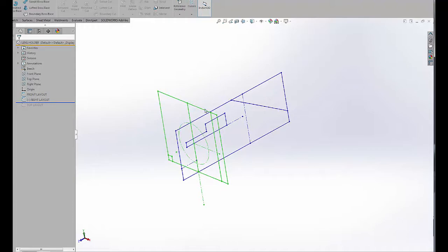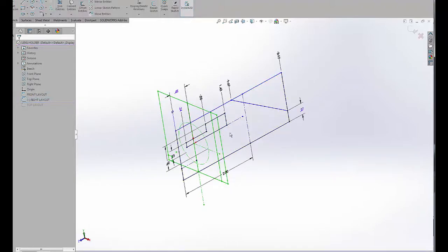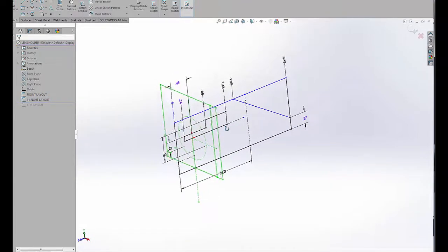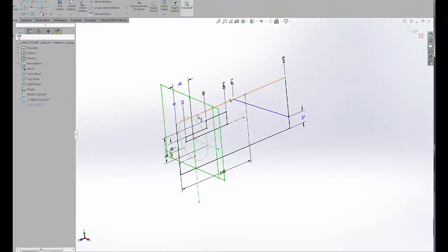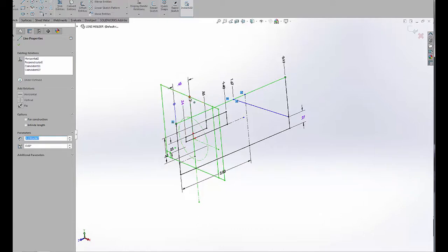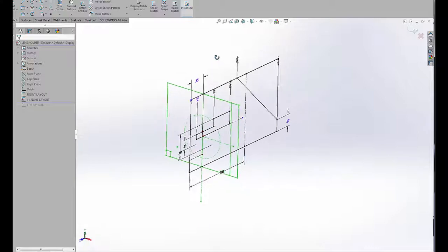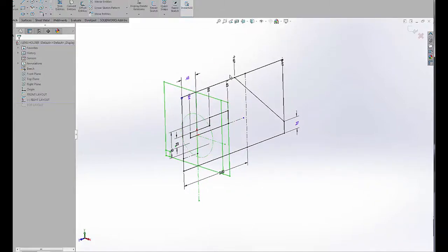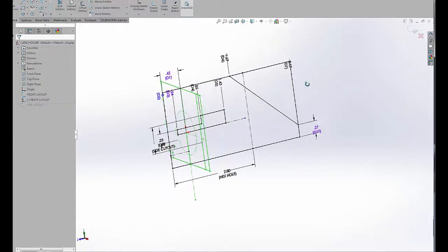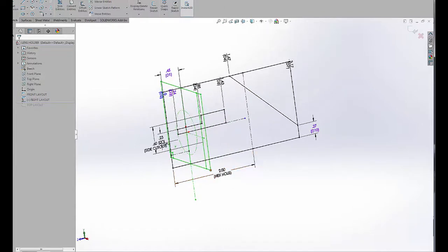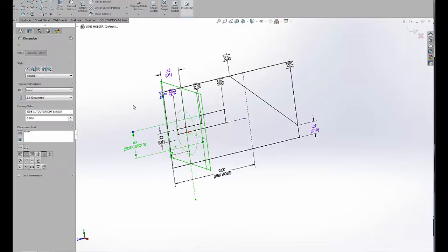So in this case, we've chosen the right view, and you'll see that this sketch has been almost fully dimensioned. Now what you want to do is avoid double dimensioning. Because the height has already been established in the front view, all we're simply going to do here is make that coincident to the front view, and now the front view will drive that height. Again, you can see here that we've given some meaningful names to some important things like the hex hole and the side cutout.